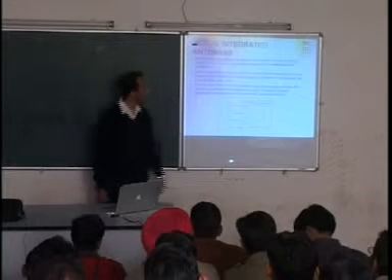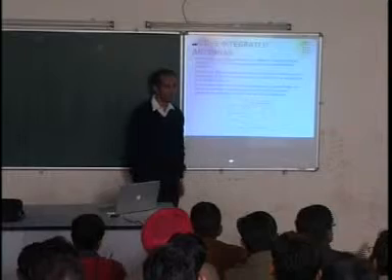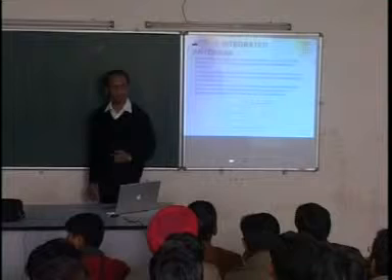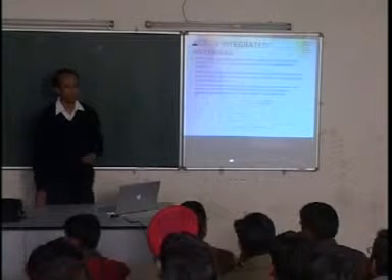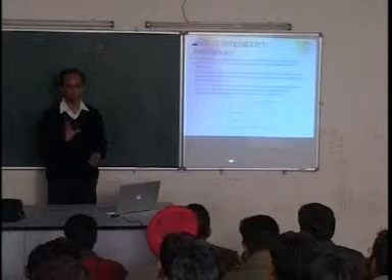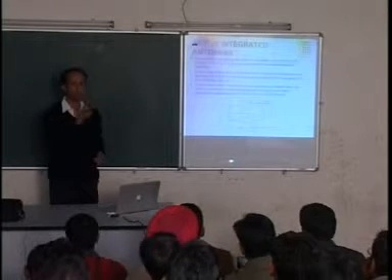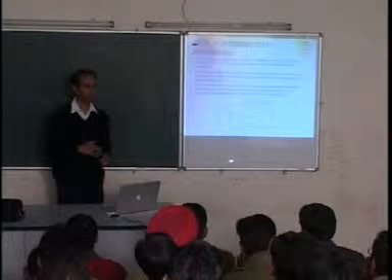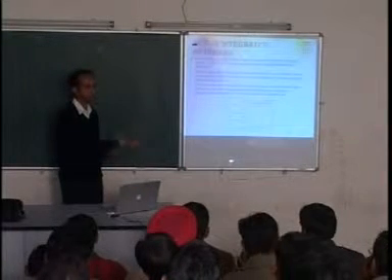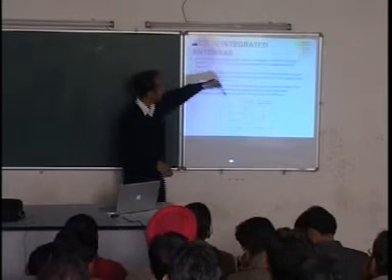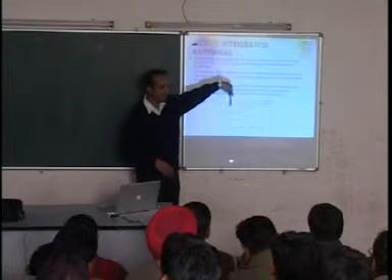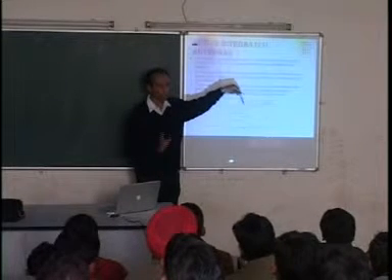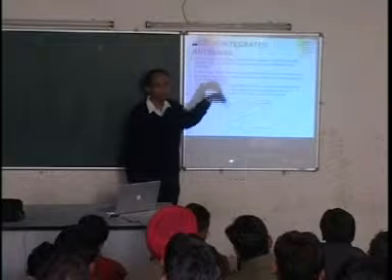Now this antenna is a peculiar antenna. It has 2 ports. Normally antennas do not have 2 ports. An antenna typically has only 1 port. If you feed a signal to that 1 port, it will be radiated out. Alternatively, if some signal is incident on the antenna, then that signal will come out through that 1 port. But here you see a 2-port antenna. This is the antenna. Why it looks like this, what is the role of that, is secondary, but it has 2 ports.